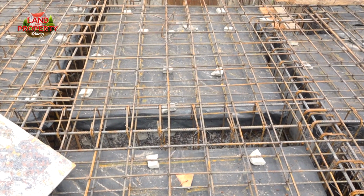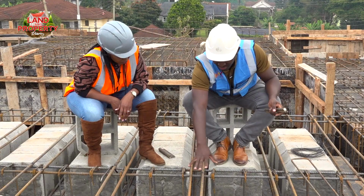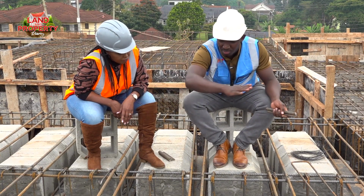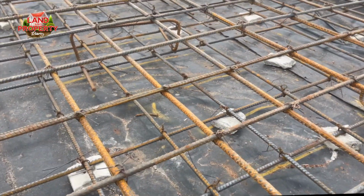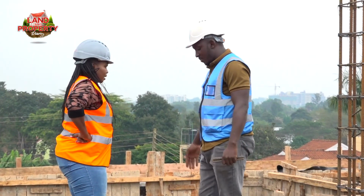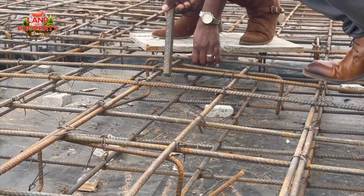When you are placing maybe the beam, you have to use a ring. But for a slab, in this case, we are doing hollow pots. We are just going to use BRC mesh on top of this. Okay. Yes. And for the traditional one, maybe you have a look at that. So this is the traditional way of putting the slab. There is this bottom one and bottom two, and you have top one and top two.